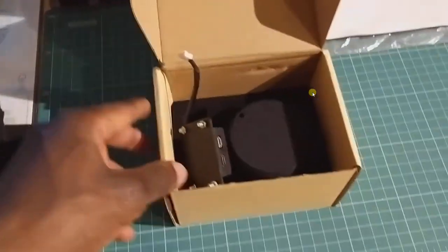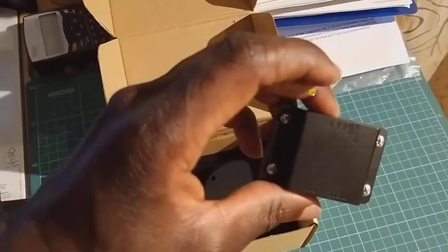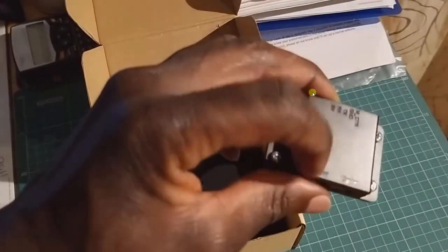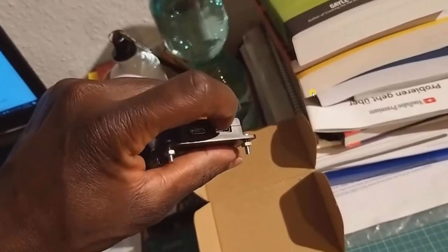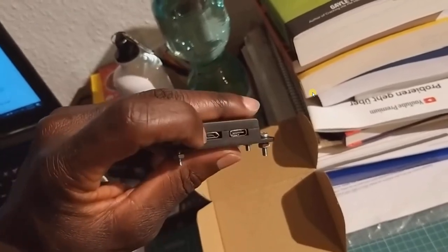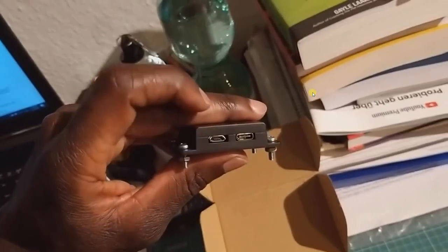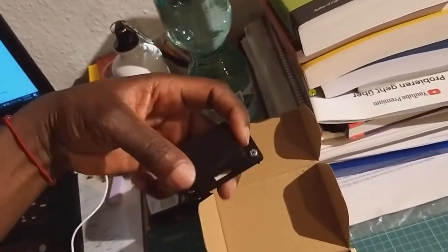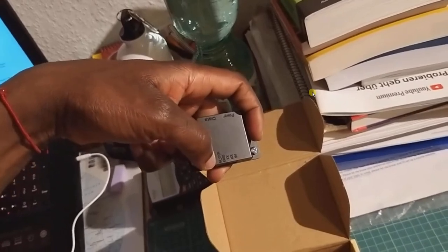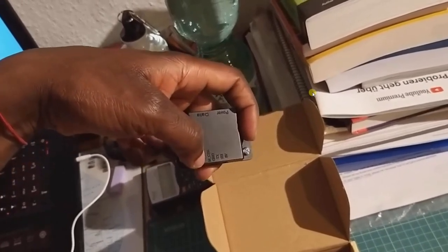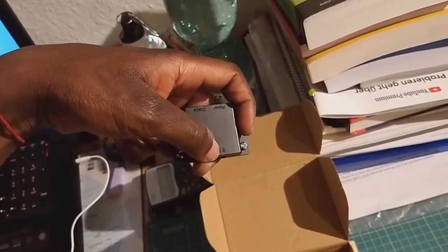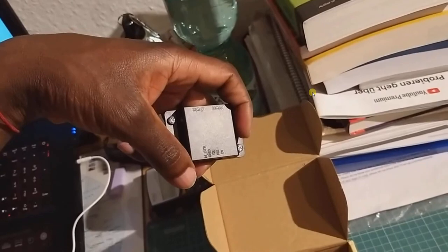First thing you see is a USB hub, some connector that has power and data on one side. The data is through USB-C and the power is through micro USB. And the other side has a serial connection that connects the LiDAR itself. It has, the first is motor control signal, and then it has ground signal, TX signal, RX signal, 5 volts. So that's the serial connection.